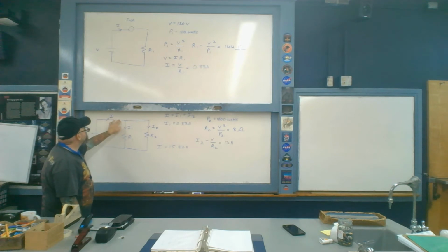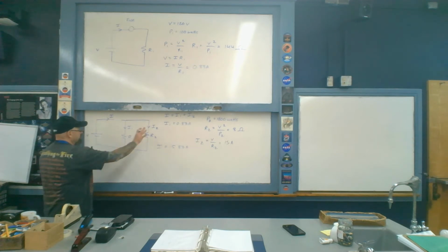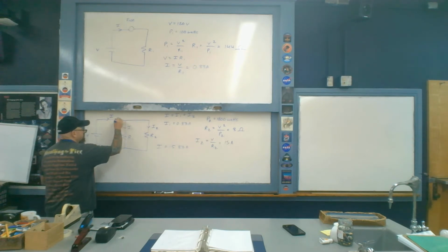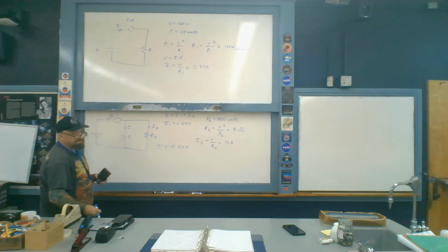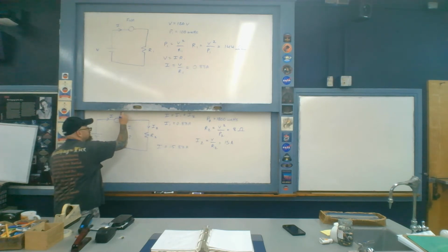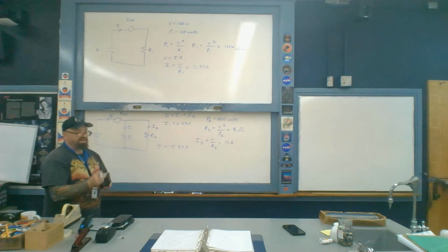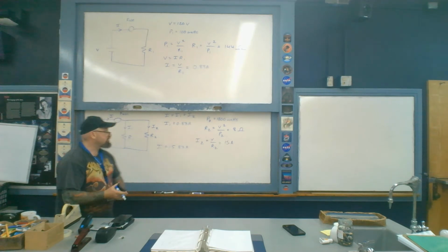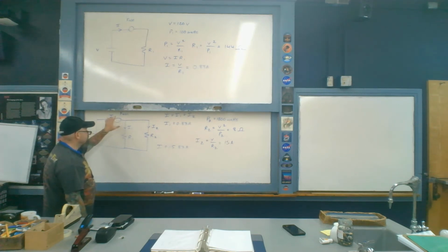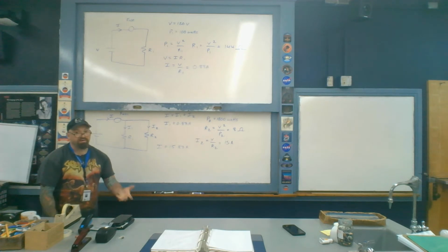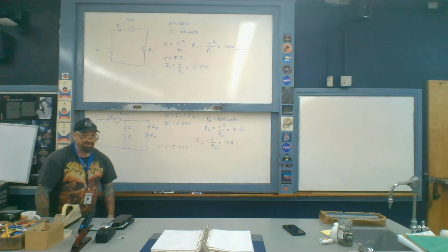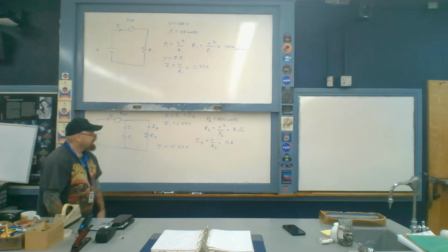This then means that what we do is we build into this large parallel circuit that we're beginning to construct here what is called a fuse. The fuse is either a small piece of wire that melts when you draw too much current I, such that it then breaks the circuit, and then therefore nothing catastrophic happens, like something catching on fire or something melting or something like that.